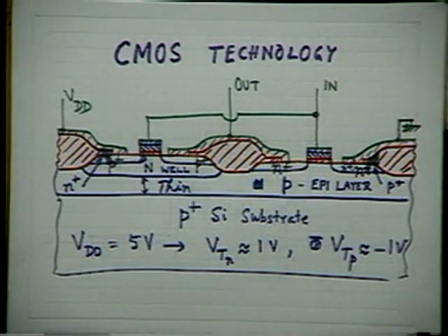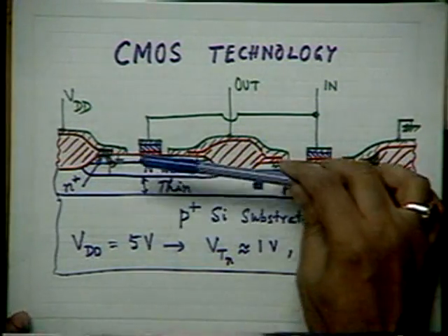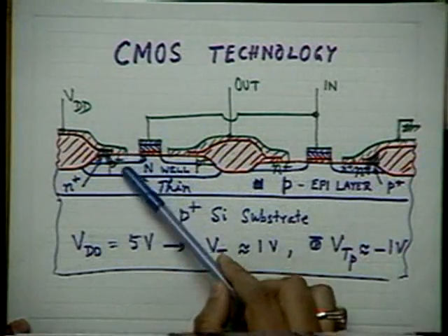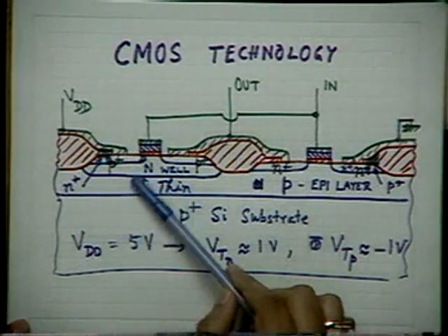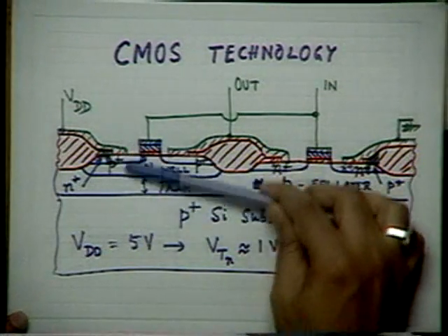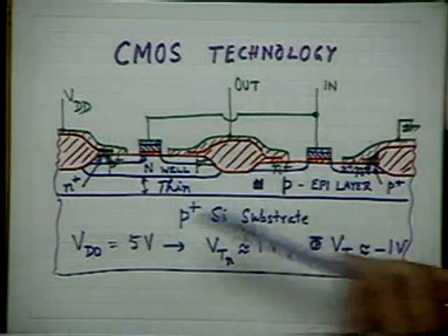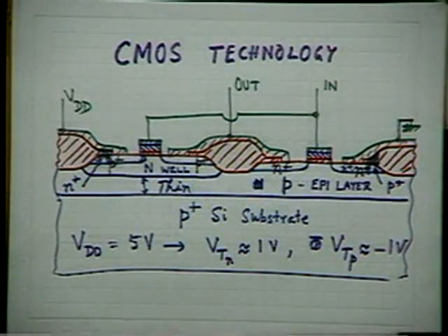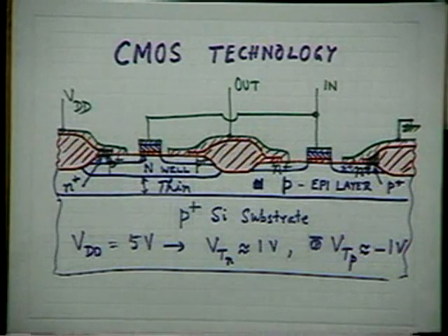So what will happen? Can you tell me? You see, there is effectively a vertical transistor here. One junction is forward biased. Then this is the middle junction. This is reverse biased. So there is practically a transistor. This is nothing but a lateral. You have seen that. That's how we describe a thyristor. We can divide a thyristor into 2 transistors, a PNP transistor and NPN transistor, where the base and collectors are merged.